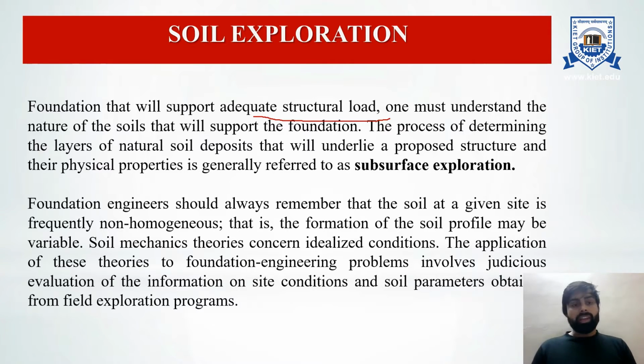The process of determining layers of natural soil deposit that will underlie a proposed structure and their physical properties is generally referred to as subsurface exploration. Foundation engineers should always remember that the soil at a given site is frequently non-homogeneous. That is, the formation of the soil profile may be variable. Soil mechanics theories concern ideal conditions. The application of these theories to foundation engineering problems involves judicious evaluation of the information on site condition and soil parameters obtained from field exploration programs.